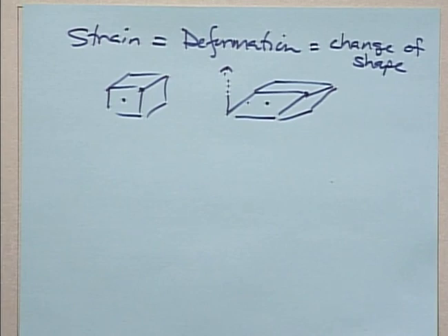And this is the mathematics on this slide, the mathematics of strain. If we postulate a coordinate system where we're going to keep track of where particles are, we can call R the location of a chosen particle P at time t reference. And then if there's some flow going on, that particle P will move to a new location at time t. And the strain will be related to the displacement function, which is the vector that connects the dots between a reference time and the location of the particle at time t. So it's this vector u.